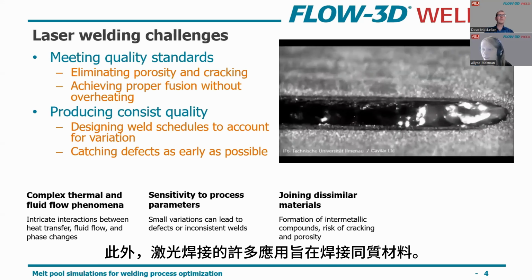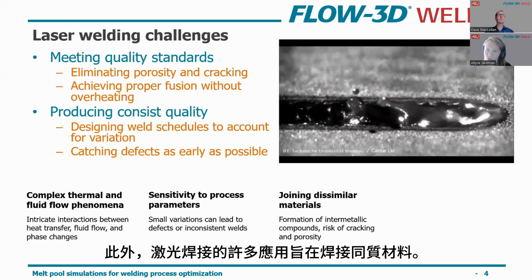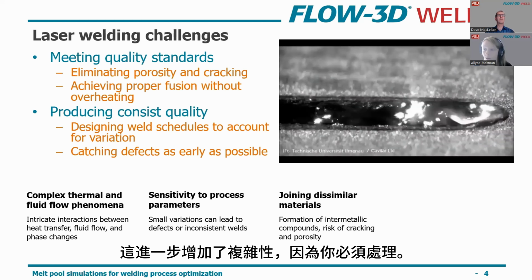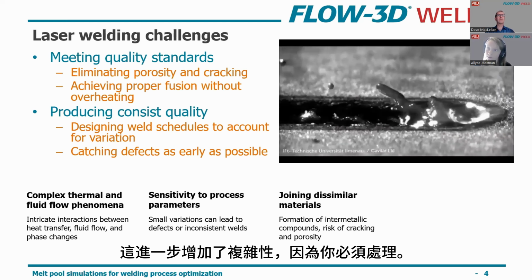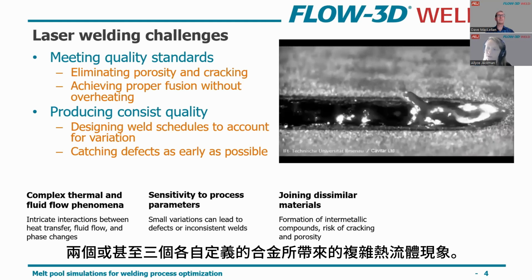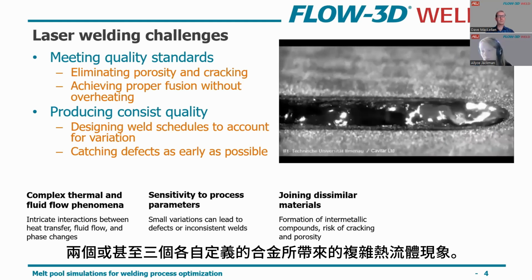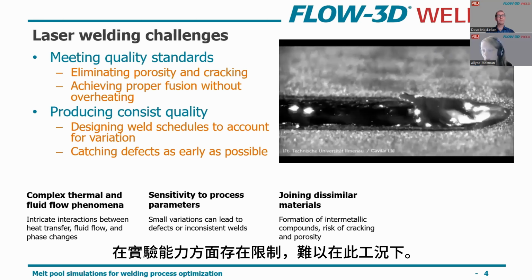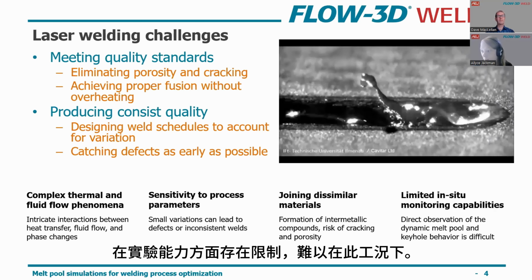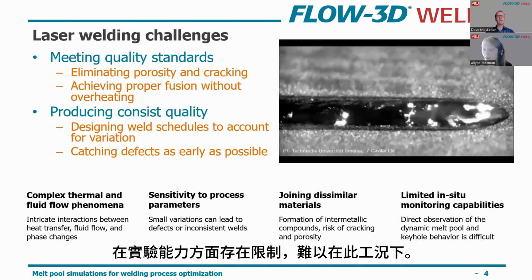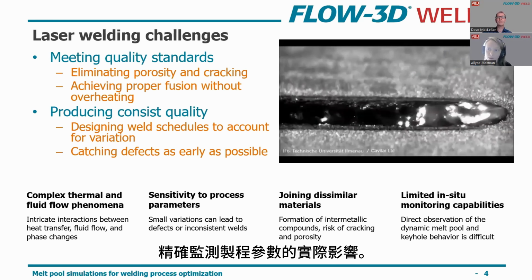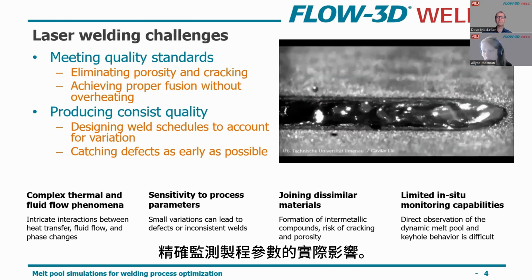And on top of this, there's a lot of applications for laser welding where they're trying to join dissimilar materials. So that creates a further complexity where you have the complex fluid thermal phenomena of 2, or maybe 3, independently defined alloys. So there's limits in terms of the experimental capabilities to really monitor the influence of the process parameters in the situation.